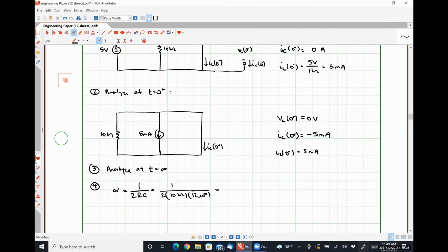So if we had a practical circuit, our inductor would have some amount of resistance. The resistance of wire as compared to a 10 kilo ohm resistor is going to be so small as to not make any difference, unless we had a mile of wire or something coiled up to make our inductor.